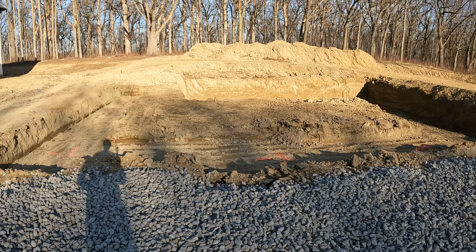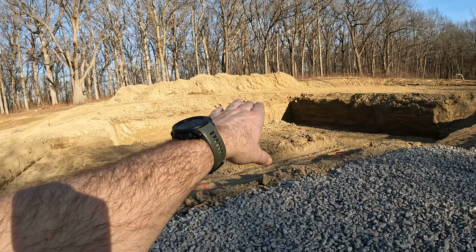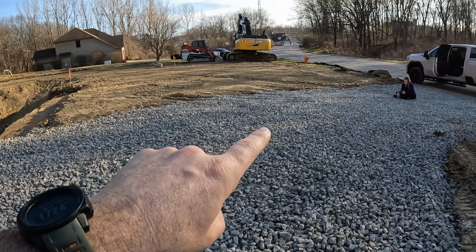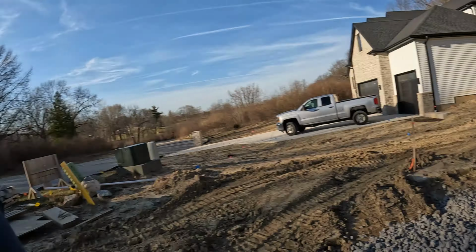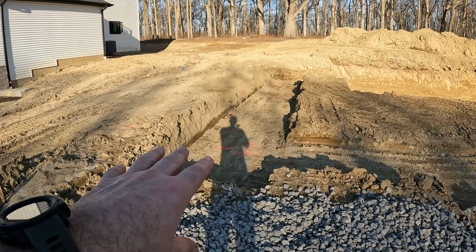That's what we do. Sometimes when you're working on a site that, as you can see, has our grade coming down to the side here, and also down from the back to the front, everything might make sense when you look at it on paper, right? Engineers draw it up, they take the existing elevation for the house next door, then they set your elevations for this. You dig to it, and sometimes you show up on site and you go, I think something's not going to work right here. And that is the feeling we had when we came in and saw how shallow the footing for the garage is.